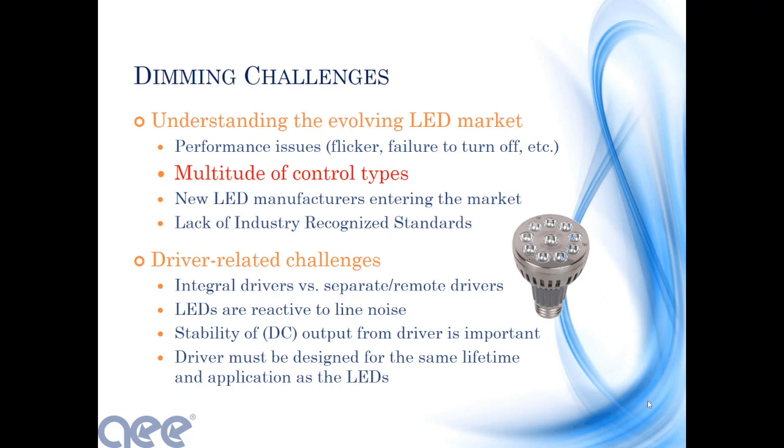And so we've also talked about some of these in the previous presentation. Flicker, those types of things. I'll talk about how the technology addresses that. Multiple control types. We're getting to the point where we're getting more and more standards for the industry as far as inrush and things of that nature. And then on the driver-related challenges on the more commercial types of applications, the integral driver to the fixture versus the separate remote driver.